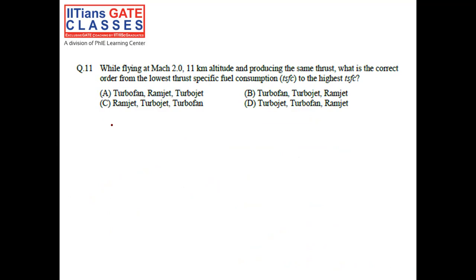Thrust specific fuel consumption, TSFC, is given as fuel consumed by the engine divided by thrust produced, m_f dot by T. Now for a turbofan engine, the thrust produced mostly comes from the bypass nozzle, where no fuel is being added.